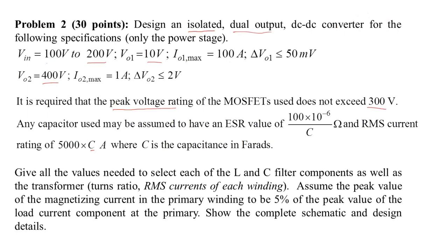Similarly, flyback will also be Vin max plus the reflected voltage, the VO over N. So likely that term will also exceed the total of 400 volts. So from all of these considerations, your full bridge is a suitable choice. You can design a forward converter, but you have to make sure that the primary to reset turns ratio is appropriately chosen, so that V switch at the maximum point is 300 volts or less.